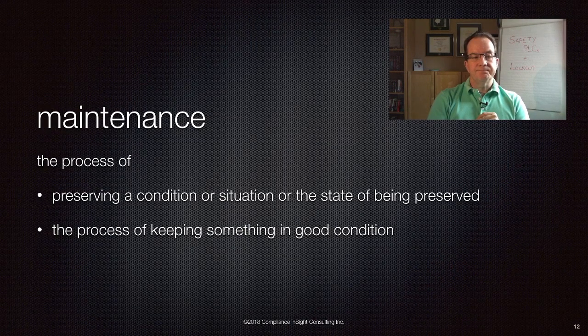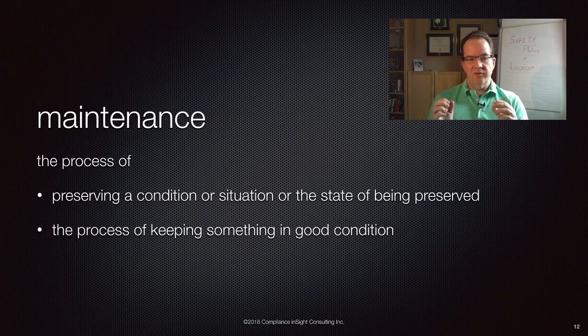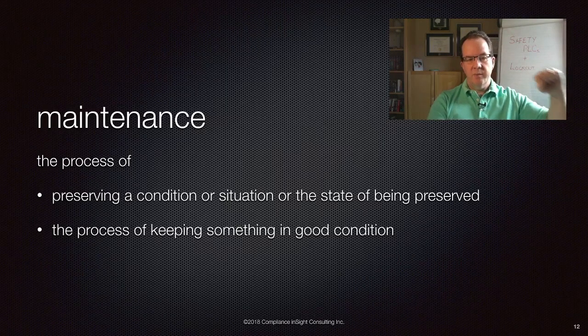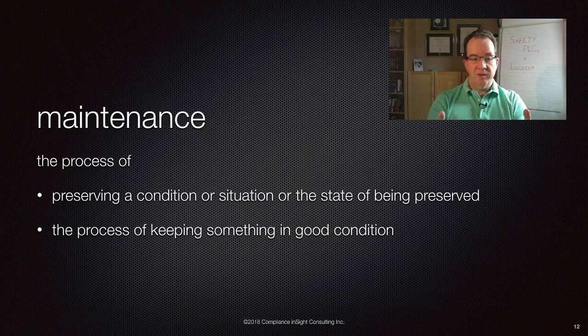So what I've generally found is that there are some circumstances where the ministry may allow you to deviate from this requirement. Section 76B kind of hints at the possibility when it says that other effective precautions necessary to prevent any starting shall be taken. However, you need to remember that this bullet has to be read with bullet A, and it's really speaking to the fact that blocking must be used along with lockout. So we're going to switch off power, isolate the energy, put a lock on it, and we may also need blocking for gravity and other things.